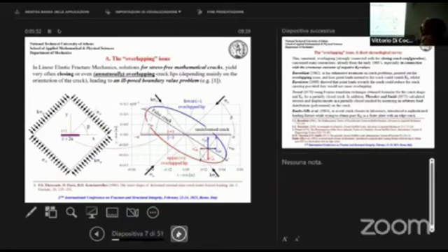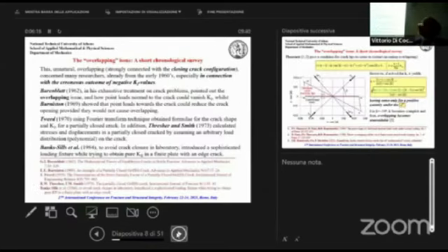What you can see here, if we solve a problem theoretically in 2 dimensions in linear elasticity, the displacement field leads to what is called overlapping of the crack lips. The upper lip, the red one, overpasses the lower lip and obtains its position. Obviously, this is not a possible case to be seen in practice. However, it is predicted clearly by theoretical solutions.